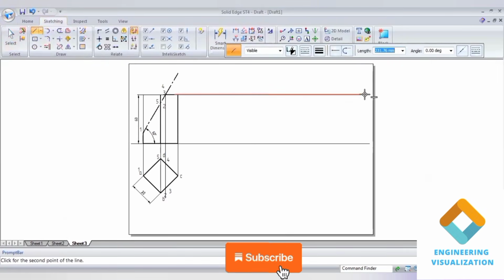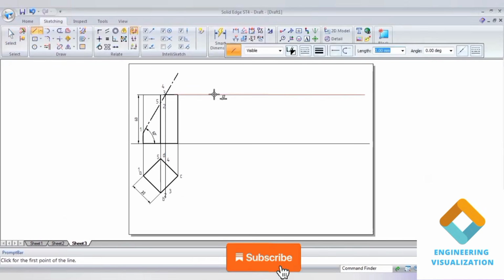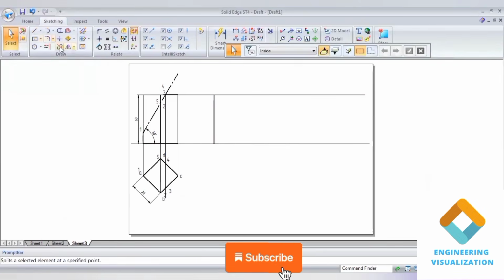Now we got the cut portion. Now we have to do the development. So draw the projection lines from here. Draw the continuous line here. Now we take a vertical edge, because this is the parallel line method, since it is a prism. So draw a vertical line. Anywhere you can take a straight vertical line.